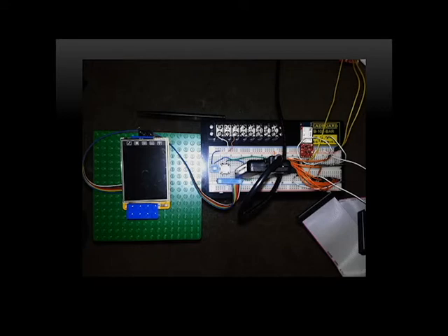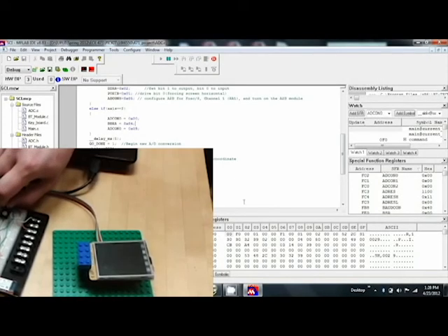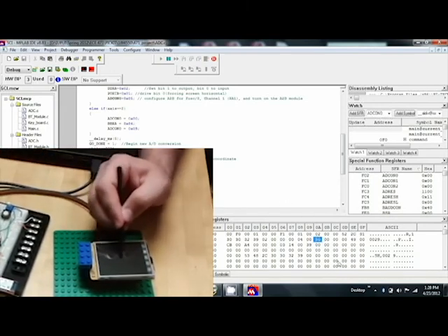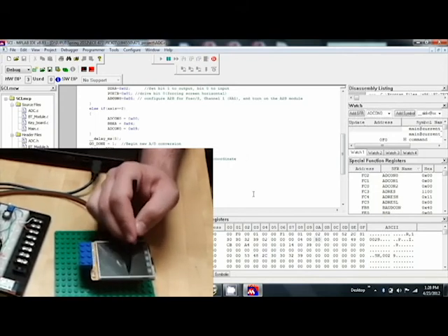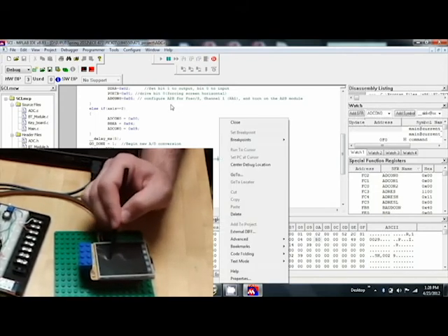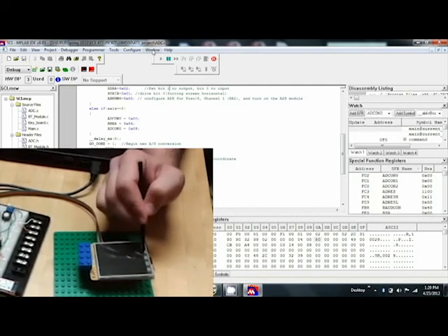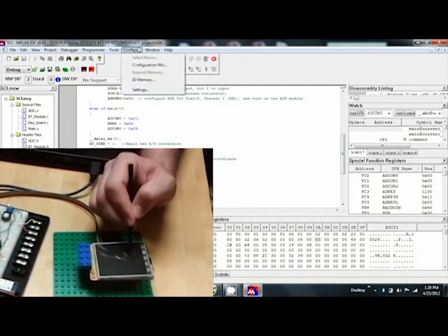Once a connection has been made, our program will continuously loop to poll the resistive touchscreen to check for a press. If a stylus is touched to the screen, arrays will be populated with recent relative movements across this screen, which can be translated into instructions to the host computer. These movements can be scaled through the use of a potentiometer. The potentiometer is also wired into an analog to digital conversion channel, which we use to multiply the value of the relative movement to give us a scaled result. The higher the potentiometer value, the further the mouse will move with a relative movement on our resistive touchscreen.